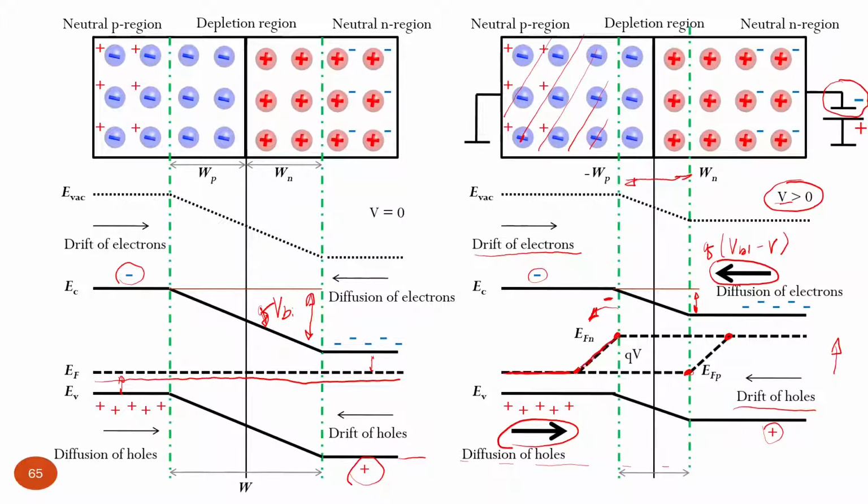So here next to the edge of the p-n junction in this region we have some excessive minority charge carriers, and they start to reduce because of compensation and recombining with majority charge carriers, which are holes. The same happens for holes, which are injected in the n-type region. So here at the edge, their concentration is high. That's why we deal with the Quasi-Fermi energy level for holes.